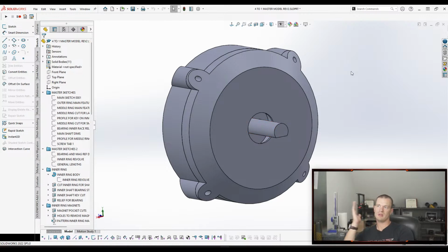The only downside I can see is that if I want to change my core geometry, I have to go back to that file. And I guess that's the same in the skeleton sketch situation, but you're not changing geometry in the skeleton sketch. You usually only put some relations in there. So I guess it's the tricky slope of what do you and don't you include in that locked layer, right? In that folder layer, whether it's the master model or that skeleton sketch folder part.